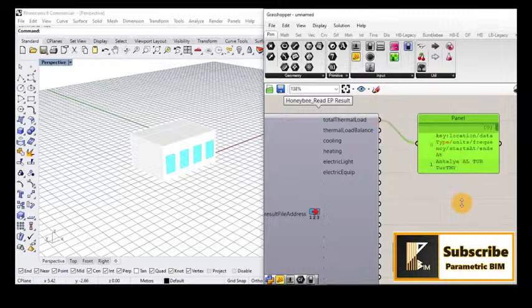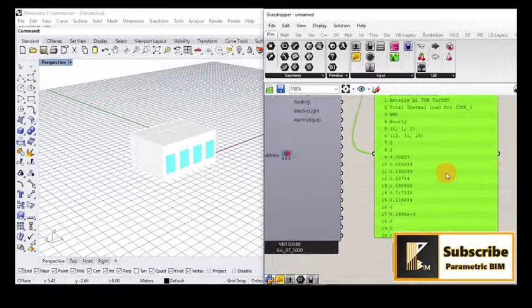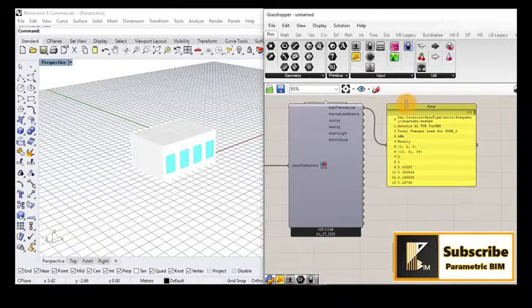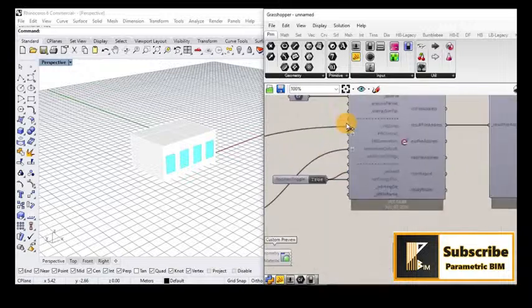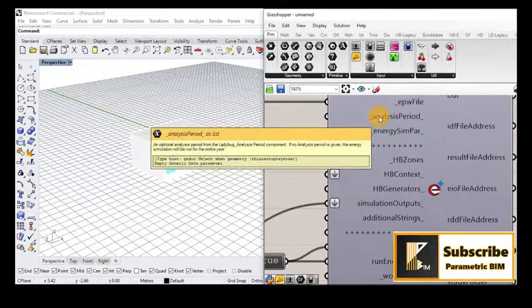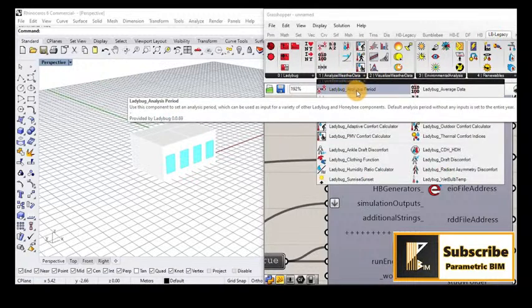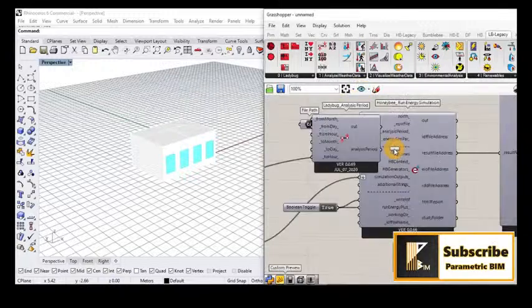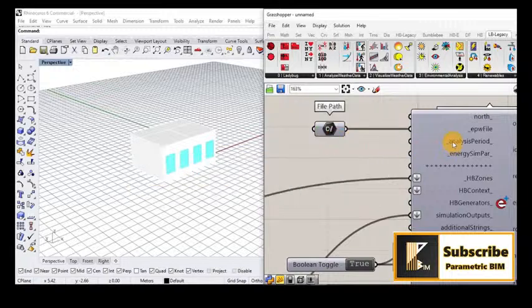And as you see, I have now a list of the total thermal results all over the year, and this is the default, all over the year, because here we have analysis period, and the default is all, an optional analysis period. You can assign that from the Ladybug. So if you want to assign an analysis period, you can come here to Ladybug analysis period and assign from month to month, from day to day, from hour to hour, but the default is about the entire year.